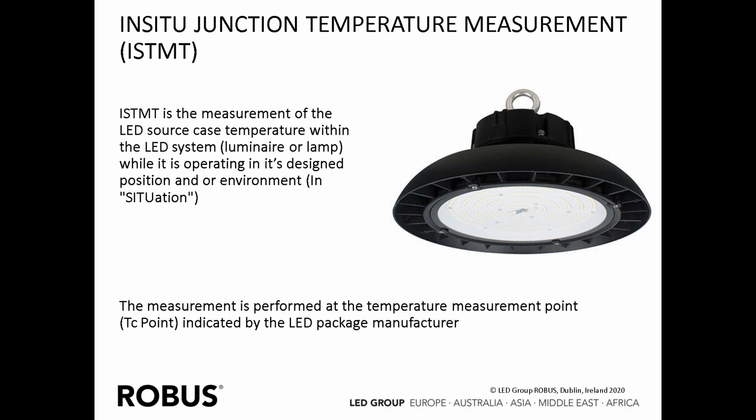The measurement is performed at the temperature measurement point, the TC point, that's indicated by the LED package manufacturer. We can't obviously put a temperature probe onto the PN junction within the LED itself, but the LED manufacturer will give instructions as to where the nearest point is that you can accurately measure the LED junction temperature.